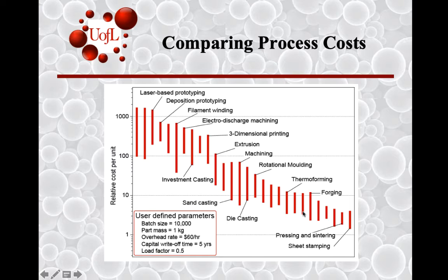So what does that mean? That it's not cost competitive to go with metal additive manufacturing? The answer is perhaps, and it just depends on this number over here. And it depends on the specific design. If a geometry cannot be built, or a material to build that geometry from is not available from many of these other competitive processes, then depending upon the value of the function of that component, this could be a more competitive process at that time. Those are the design considerations that go into additive manufacturing. We'll look at that separately in another course.